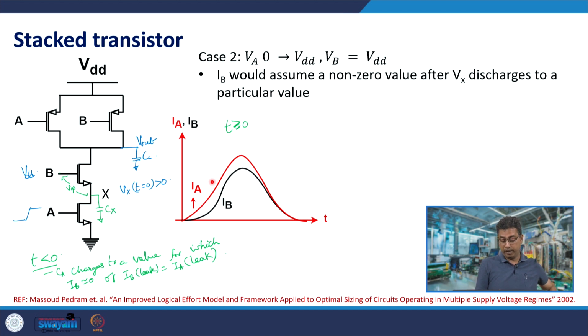It rises further when the input voltage VA is larger than a certain value, because the near threshold or subthreshold current would increase as an exponential function with respect to input voltage. So, therefore, the increase seems sudden. The current switching seems to be sudden when the input switches.